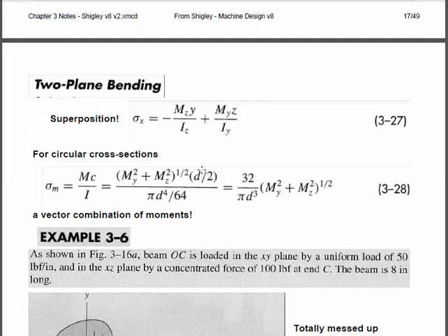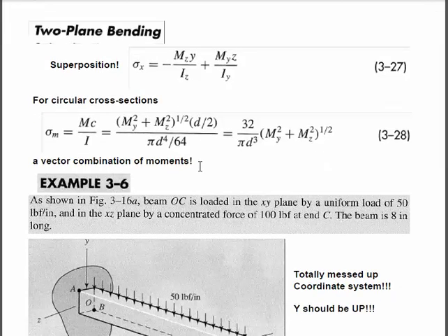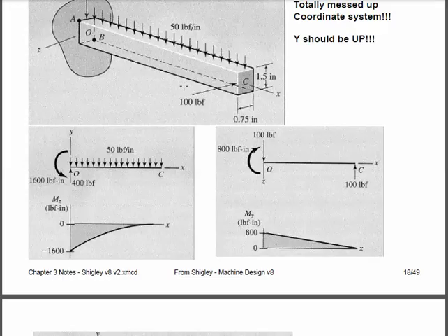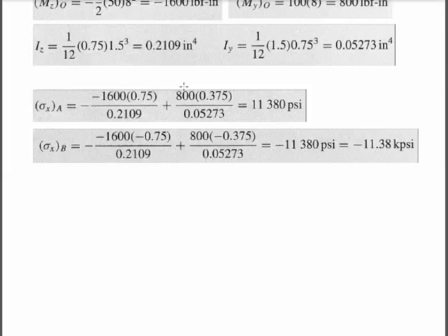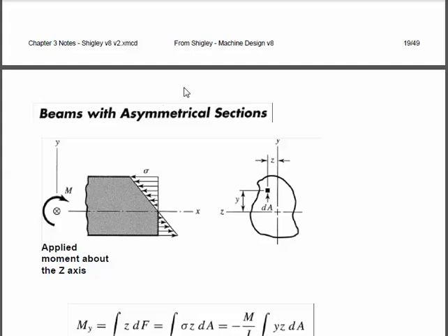I don't really anticipate asking you to do that piece on a test, but be ready to use moment of inertia on a test. We could have bending in two different planes, and then the stress at any particular point can come from superposition, which we've now defined. We can calculate the stress because of bending about the z direction and bending about the y direction, using the two moments of inertia, just by adding together and being careful with the sign, because knowing which piece is in compression and which is in tension matters. Very little I need to say about MC over I.